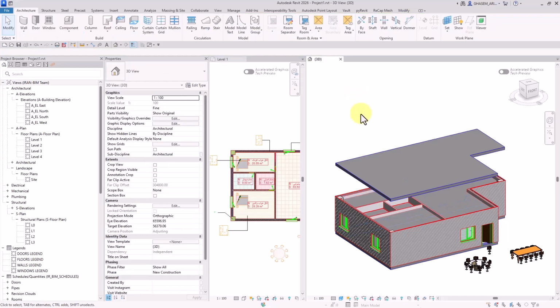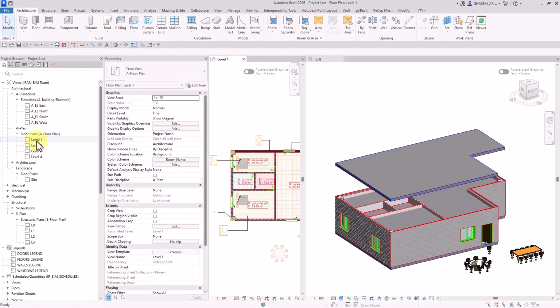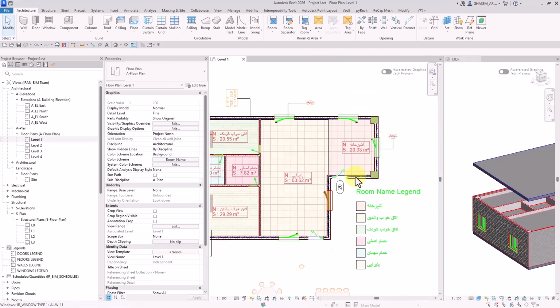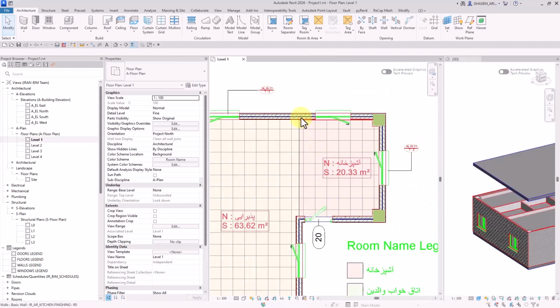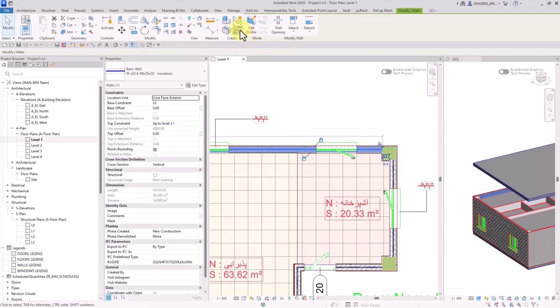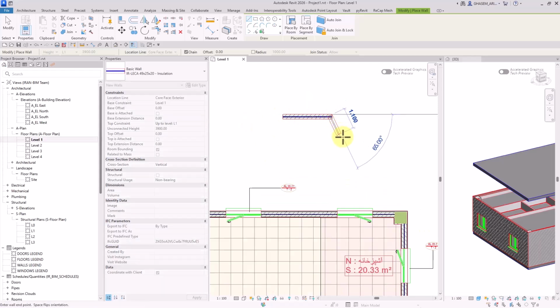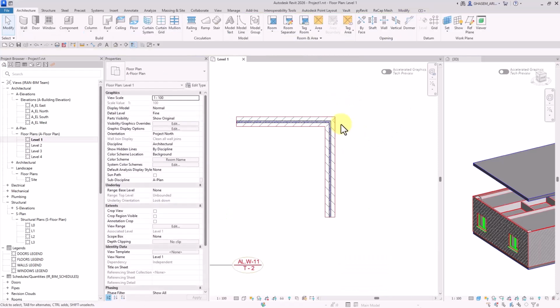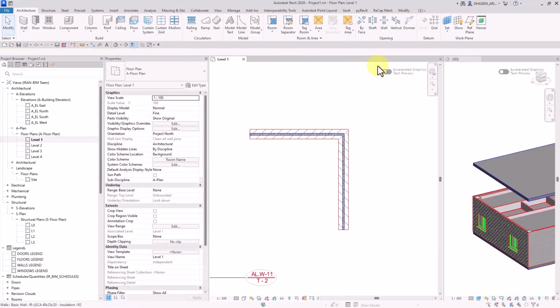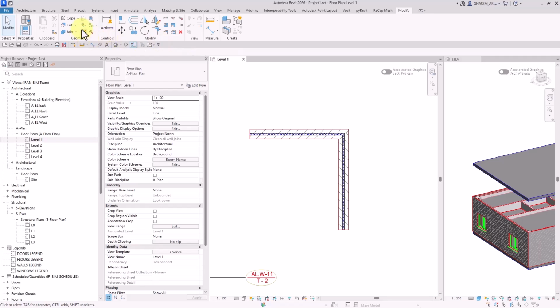I guess we have some changes in wall join as well. For example, let's see what we got here. I'm going to select this wall, create similar, and try setting another wall here, an L-shaped form maybe, quite randomly. Now, exactly like the rest of the items that we talked about so far, the sub-items that we have for the wall join were set in the option bar previously, but now we can find all of them in the ribbon.